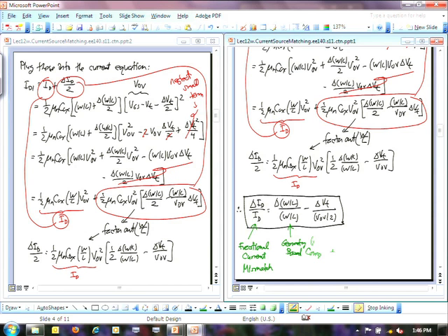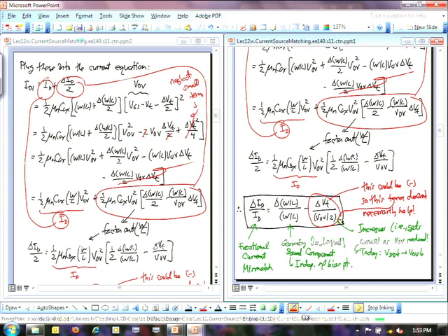Slew rate, how fast your op amp can actually keep up with a certain square wave. Of course, very important stuff. Sounds like a digital thing, but it's really an analog sort of thing, because you've got to go from analog to digital. It's an op amp that will generally make that transition for you, so the op amp has to be able to put out a nice square wave by the end of that.